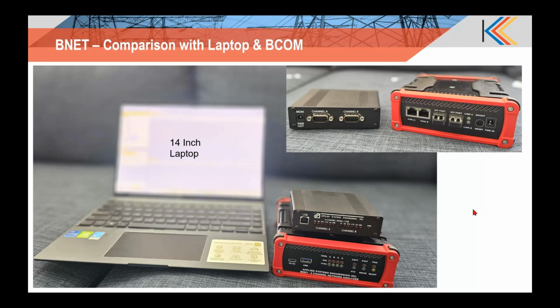And it looks quite portable. And I also see that, you spoke about the SFP ports. So, what's the need for an SFP port instead of making those a default Ethernet or fiber option? So the SFP port allows you to connect either to a fiber port or an Ethernet port, right? Nowadays switches come in different forms. They also mostly support SFP ports. So if the process bus supports fiber optic, then you will have to connect these ports to a fiber connection. So here you get the flexibility of using any of these, right? You can have an SFP connector with Ethernet or an SFP connector with fiber optic. By default, the unit comes with the fiber optic SFP connectors.